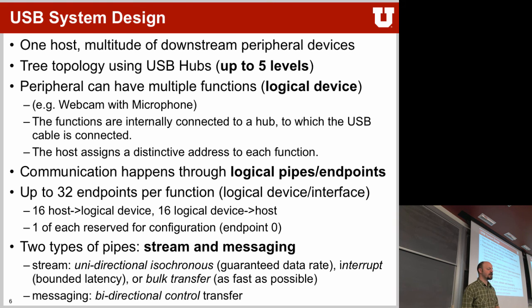USB can also have up to 127 different devices. If you have more than 127 devices, it won't work anymore. Sometimes it even stops before that. We did some tests in our lab where we could barely get 70 devices enumerated on one of the USB buses because the software in the back end did not accept more of them. So physically, the protocol can probably handle it, but the software, the drivers, could not.